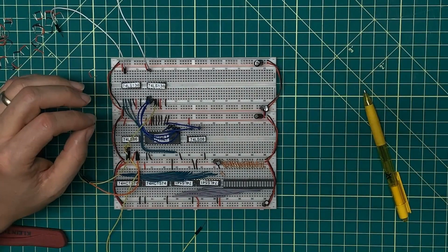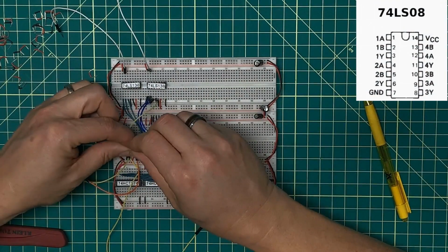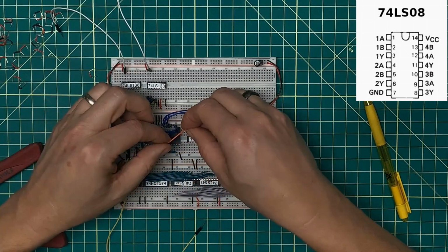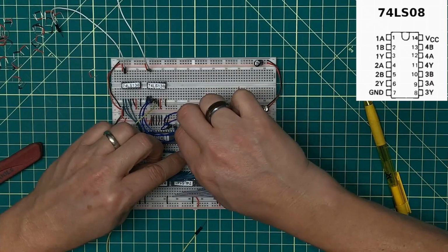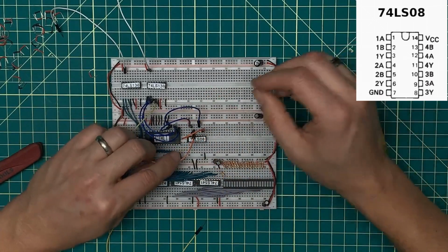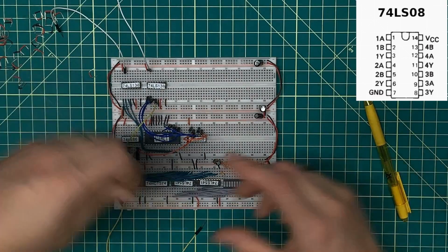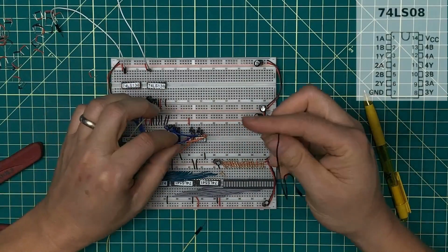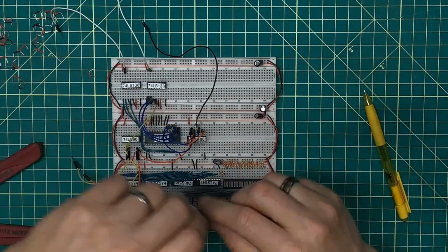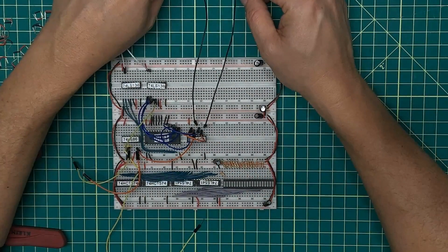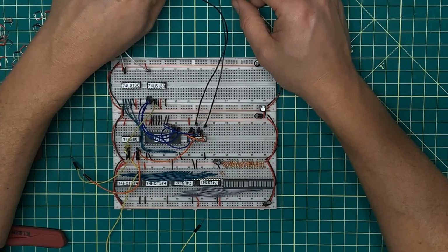I'm looking at my diagram up here with the inverted clock. So I'm going to take this clock signal here and drop it up there, and then I'm going to also extend it from there over. Something is not aligned. You know, it is aligning right. And so my two outputs here are, let me just check my wiring, bit 0 and bit 1 for the AND latch, I'm sorry, for the load increment decrement.